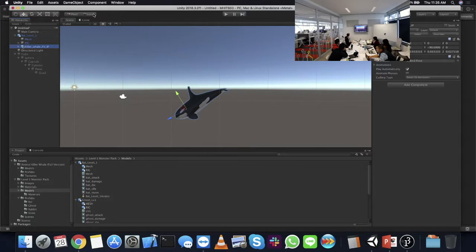So what I can do is click on that, and that will move it into global, which is in world space. You'll notice now that it doesn't point in the direction that the whale is facing, it just points in X and Y, and I can shift that whale out in that position. What we'll notice though is, before, if I move this in local, only the X value of the position's moving. But if I change this to global and then shift it, you see both the X and the Y values are moving because it's moving it now in the world space.